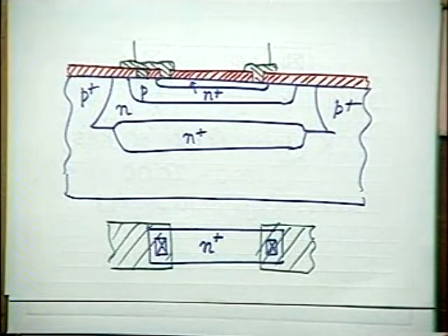On the other hand, if you are interested in realizing very high resistors, quite often needed for certain leakage, for example, when you are planning your TTL logic, between the base and ground, quite often we put a very high resistance. Why? To reduce the storage, to offer a leakage path to the ground. And this resistance's absolute value is not that important. One thing is important, it should be very high, and its TCR is not that important.